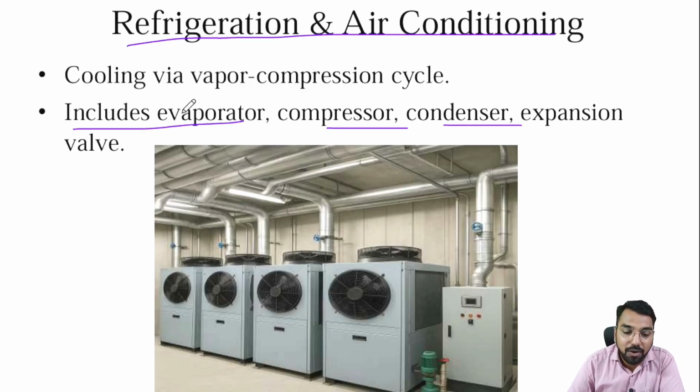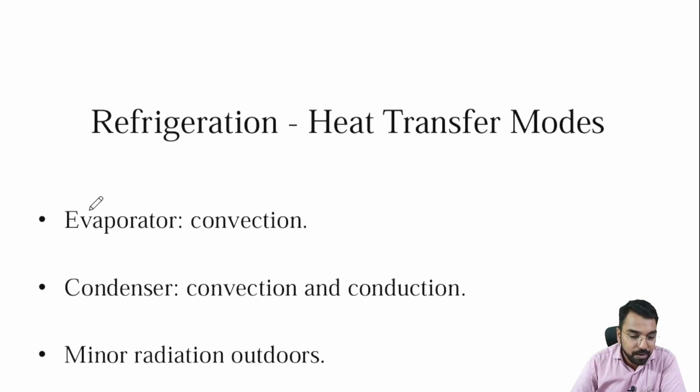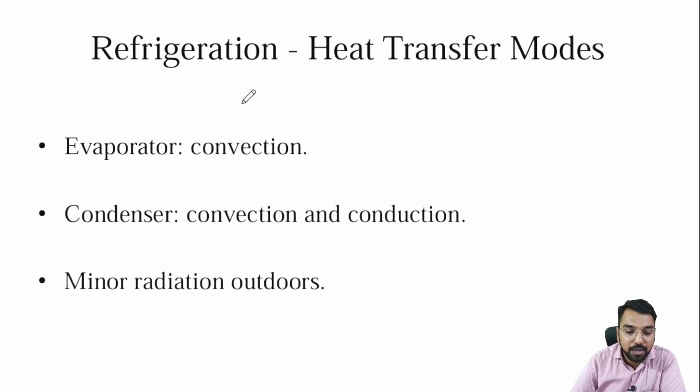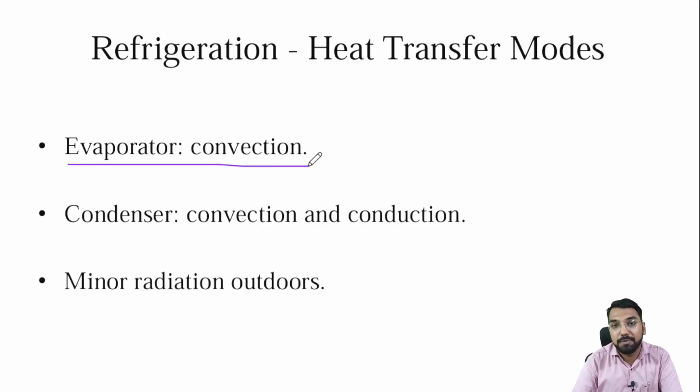So all these components will work according to their working, but the main principle of heat transfer or heat exchange is there, and these three modes of heat transfer are applied here also. So, refrigeration heat transfer modes. In the evaporator, convection heat transfer takes place.